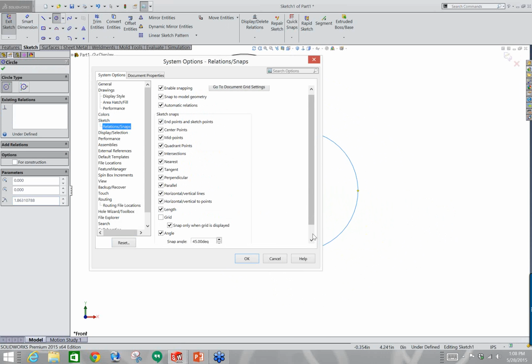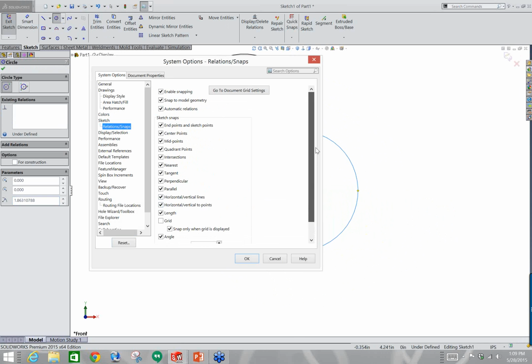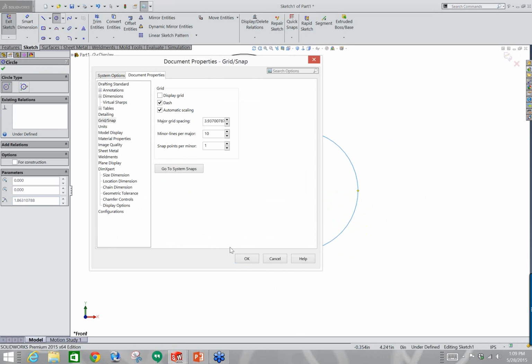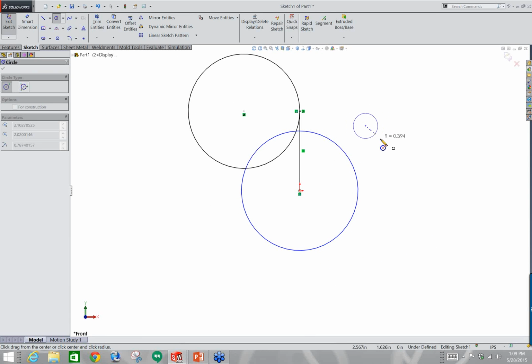You can snap to. We don't want to snap to a grid. Never mind. No, we can have it so that when we hold the shift key down as we're sketching our geometry out, we can actually snap to unique values. So again, not there. Okay. Oh, okay. My snap at the moment is set to metric. So the values we're seeing here is we're in an inch document, but my snap is set to metric, so that's why you're seeing it.